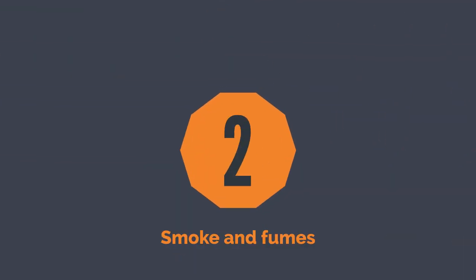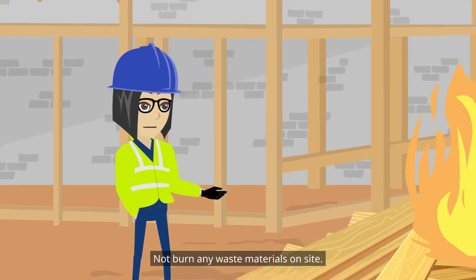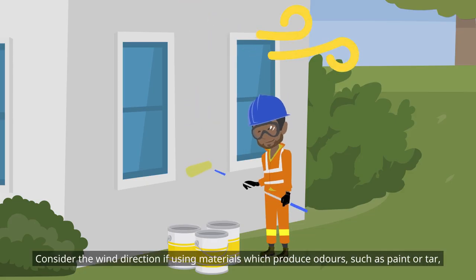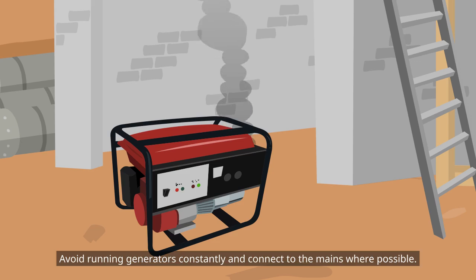Smoke and fumes. To minimize impacts from smoke and fumes, you should not burn any waste materials on site. Avoid idling machinery and turn off when not in use. Consider the wind direction if using materials which produce odors, such as paint or tar, and keep lids on containers when not in use. Avoid running generators constantly and connect to the mains where possible.